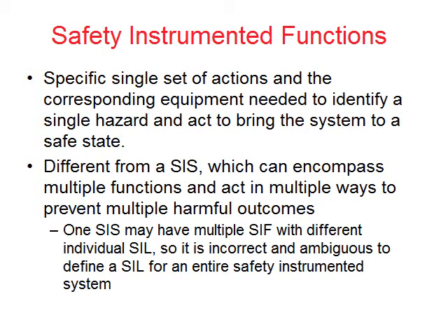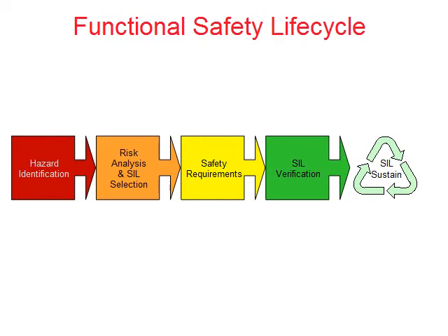So often we'll also talk about safety instrumented systems, and the way to think about it is a safety instrumented system contains one or more SIFs, and specific risk reduction targets or SIL levels are defined for the safety instrumented functions themselves. So in the standards, there's a process called a functional safety life cycle, and it looks to identify, design, maintain systems and processes to mitigate these risks and hazards we're talking about.